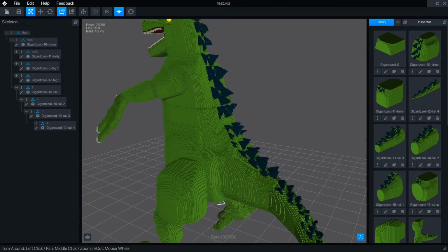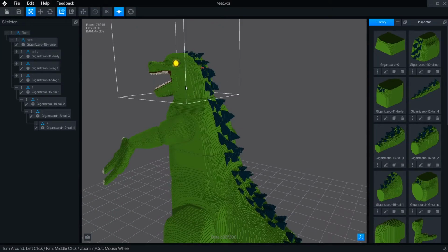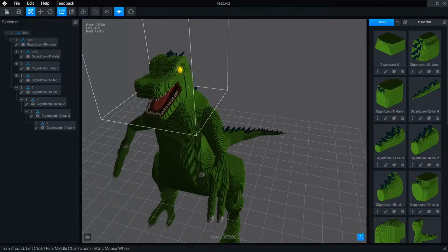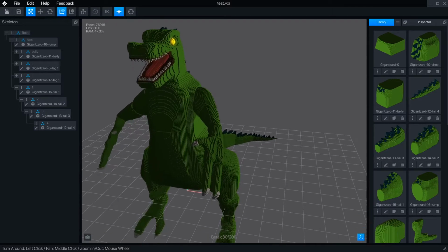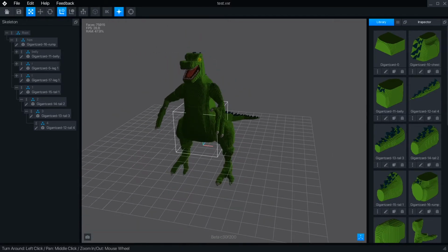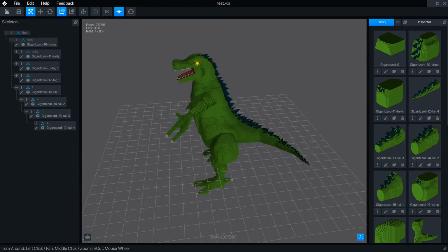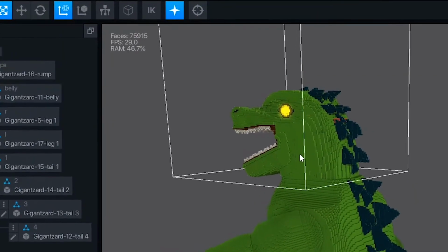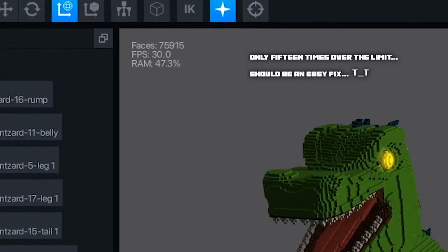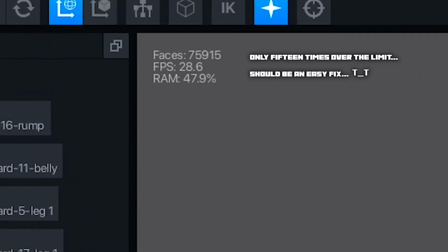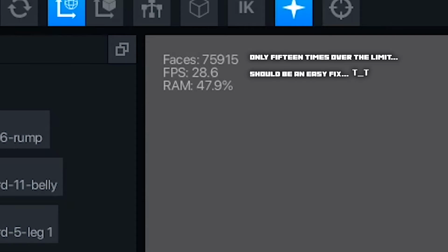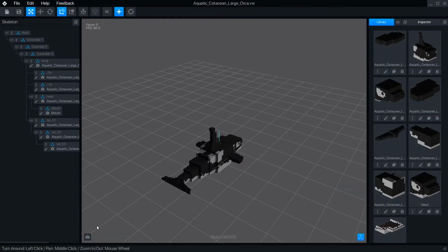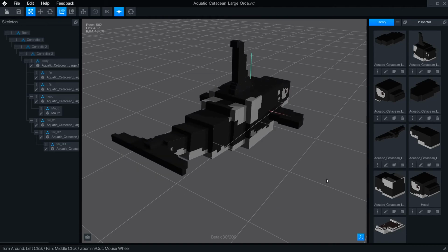As you're designing, keep in mind that VoxEdit optimizes its files by combining rectangular areas into a single face, or a pair of two triangles. Every bump or non-rectangular plane will add additional faces and twice as many triangles. The Sandbox Marketplace and Game Maker currently only officially support models with up to 5,000 faces or 10,000 triangles. Objects that are super detailed like my giant lizard monster will not be possible to upload to the marketplace. Finding ways to square rounded areas into blockier shapes helps reduce the face count and match the Sandbox style better.